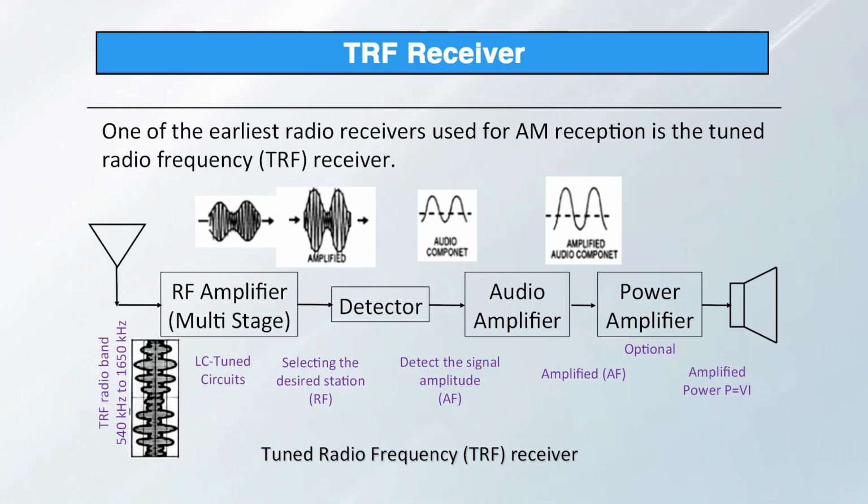The characteristic is that it typically operates in the audio frequency range of 20 Hz to 20 kHz and has a linear response to faithfully reproduce the audio signal. It may consist of one or more stages of amplification to achieve the desired output level. Signal fidelity and low distortion are critical to ensure accurate reproduction of the audio signal. Impedance matching with the output transducer, speaker or headphone, is essential for effective power transfer. The next component is the power amplifier.